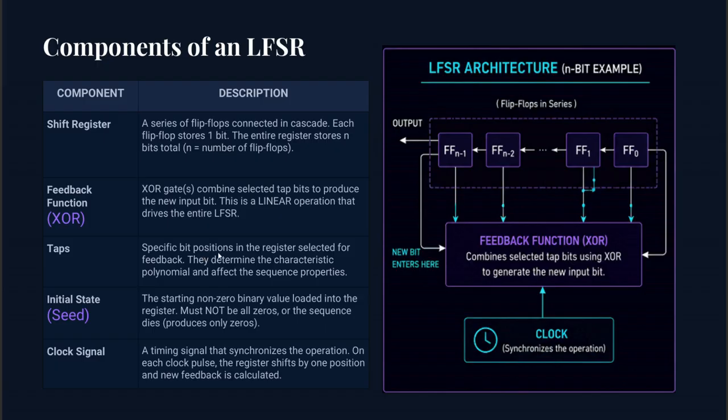Next we have taps. Taps are specific bit positions selected for the feedback calculation. Different tap positions generate different output sequences and determine the mathematical behavior of the LFSR.